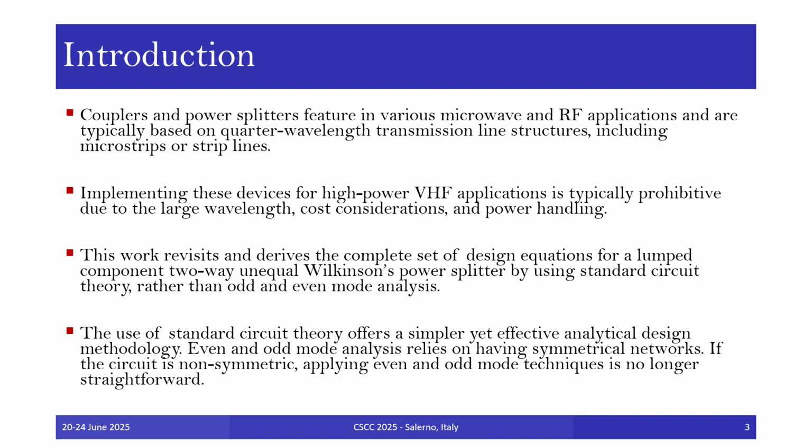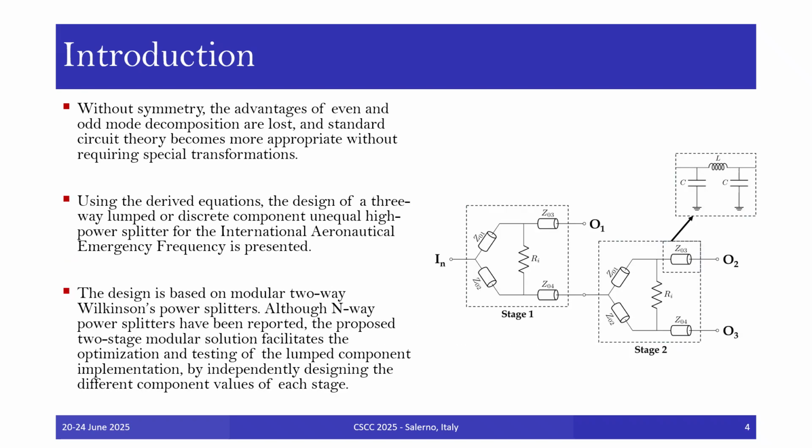The use of standard circuit theory offers a simpler yet effective analytical design methodology. Even and odd mode analysis relies on having symmetrical networks. If the circuit is non-symmetric, applying even and odd mode techniques is no longer straightforward. Without symmetry, the advantages of even and odd mode decomposition are lost, and standard circuit theory becomes more appropriate without requiring special transformations. Using the derived equations, the design of a three-way lumped or discrete component unequal high-power splitter for